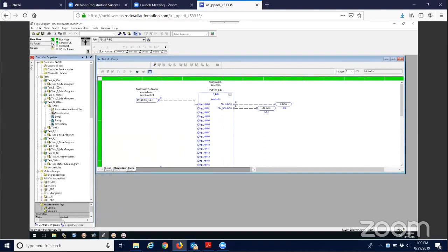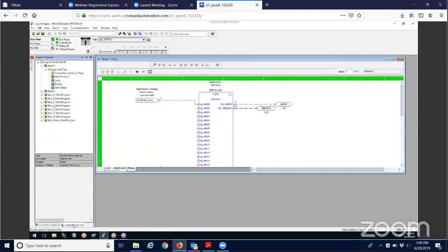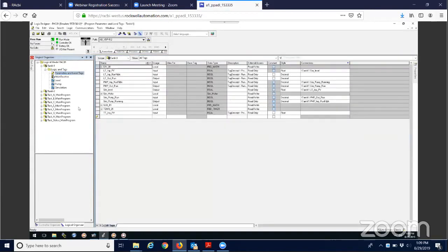So I'm going to go back to the logical organizer, and let's say, okay, tank one, I'm going to open up my parameters. All my tags and all my stuff are local parameters in this task. Here, my LT input process, this is my tank level input process variable. Right now, I'm connected to tank one sim. But let's say, okay, I really want to connect this to my real world IO point now. Notice I'm online too.